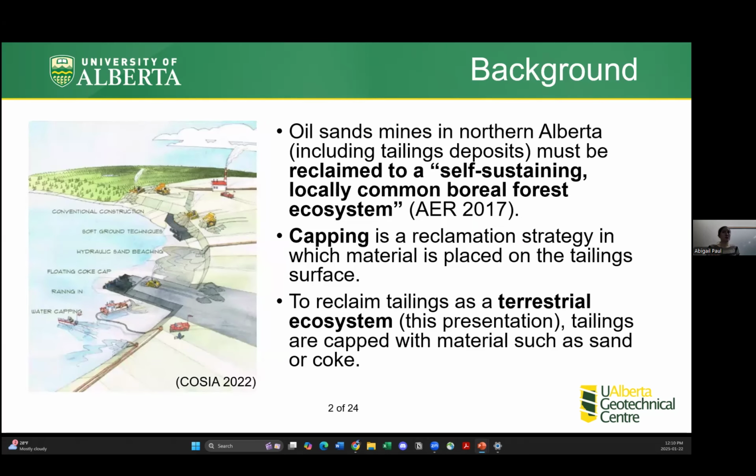And one step in reclaiming those deposits is capping, which basically means placing a layer of something on top of the tailings. So for example, if the goal was to transform the deposit into an upland or a wetland landform, the tailing surface would likely be capped by placing tailing sand or petroleum coke on top of it.